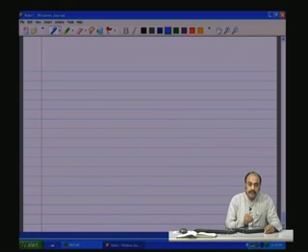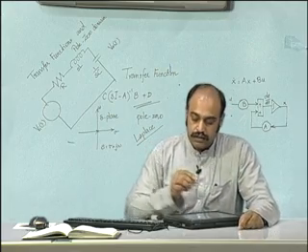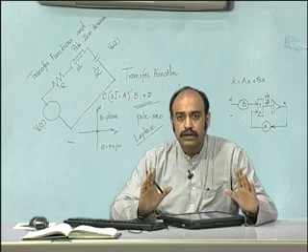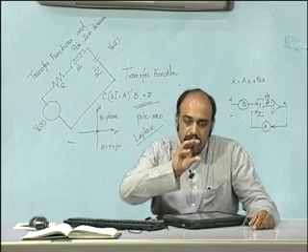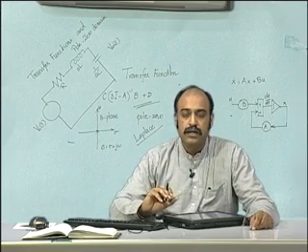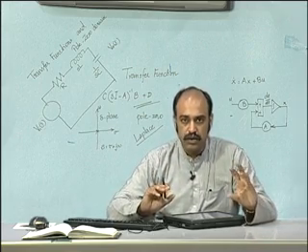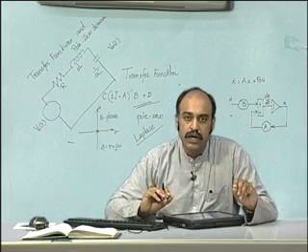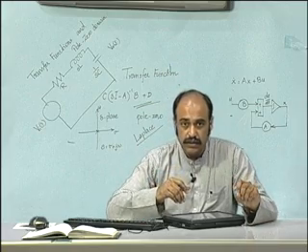Now, what is important to note at this point is that the state equation is a complete description of the system along with the dynamic behavior, and out of which, under some constraints, we have shown that when d by dt is replaced by j omega, if the inputs are sinusoidal, then we can get the sinusoidal steady state equation from the state equation.